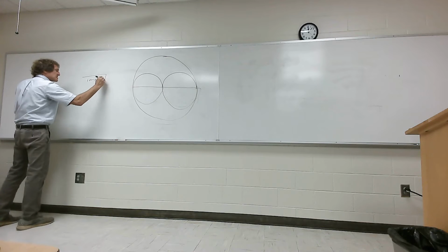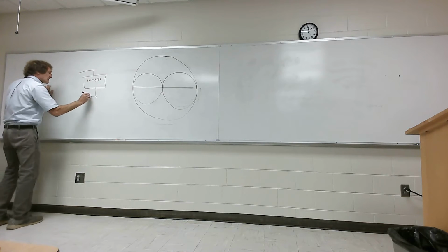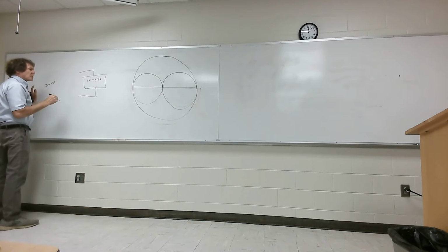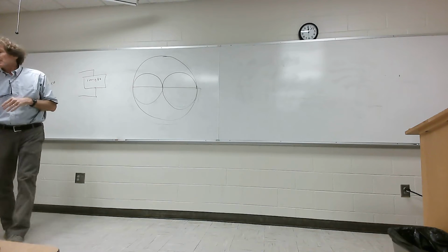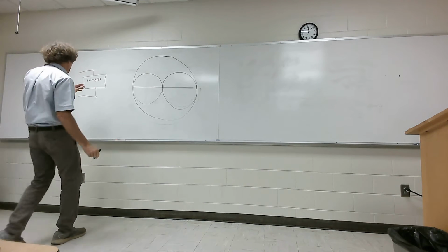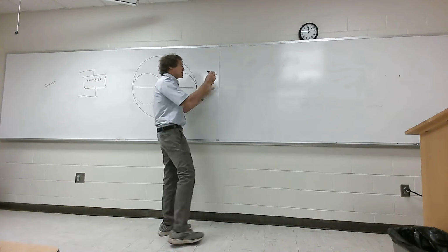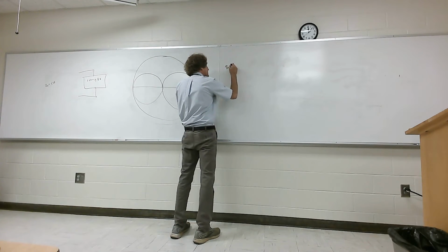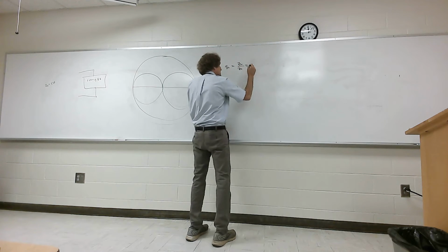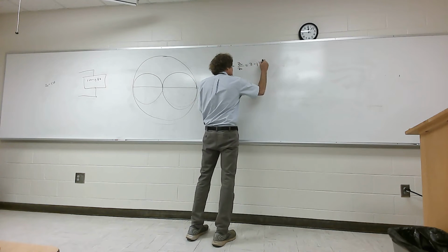To be matched into Z0 equal 50. Now we're going to do the design where we put an inductor in parallel and a capacitor in series. So the first thing is we take this and normalize it as before, and we get the normalized ZL, which is capital ZL over Z0, and that's equal to 2 minus J 1.6.